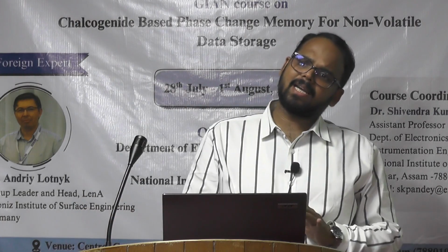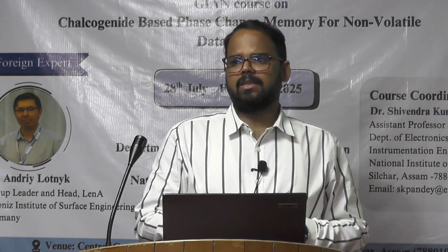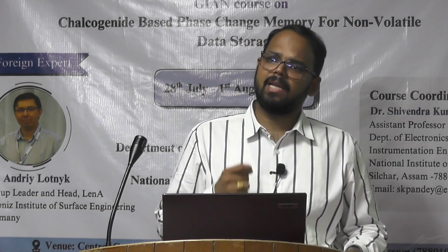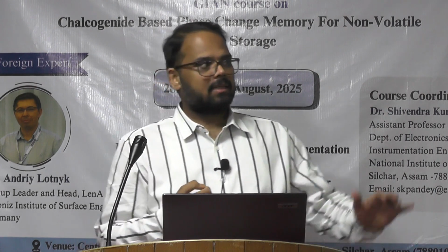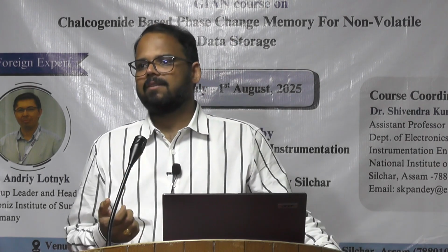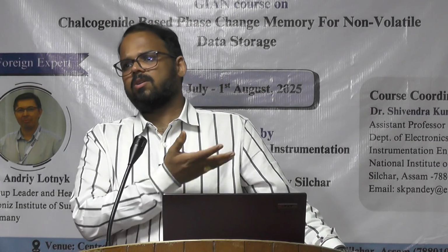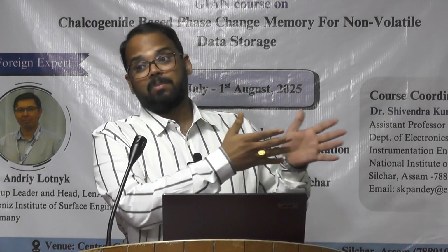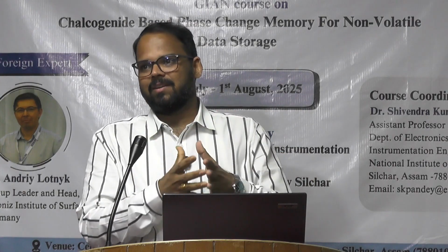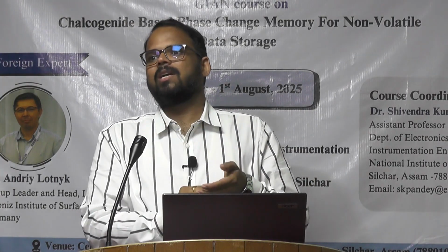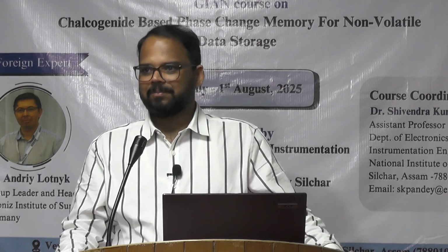So pulse characterization means when we figure out a high speed transition, we need to check at high speed, and then we need it for more programming aspects. And with this kind of a study, it could be identified what is the minimum amount of current. You can see that it is in the order of microamp, very less. That too for a bigger device. We have not developed these devices with appropriate lithography and very small contact size. If you do it that way, then you can reduce that also. Okay.